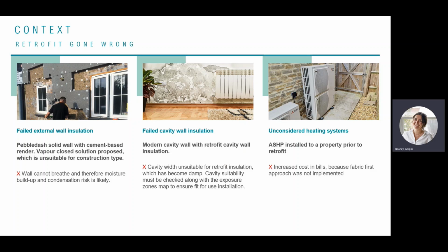Typically, these walls need to breathe. The render and then also this external wall insulation will be preventing that, and the likelihood is that will cause problems in the internal environment. So again, a very expensive mistake going on there.